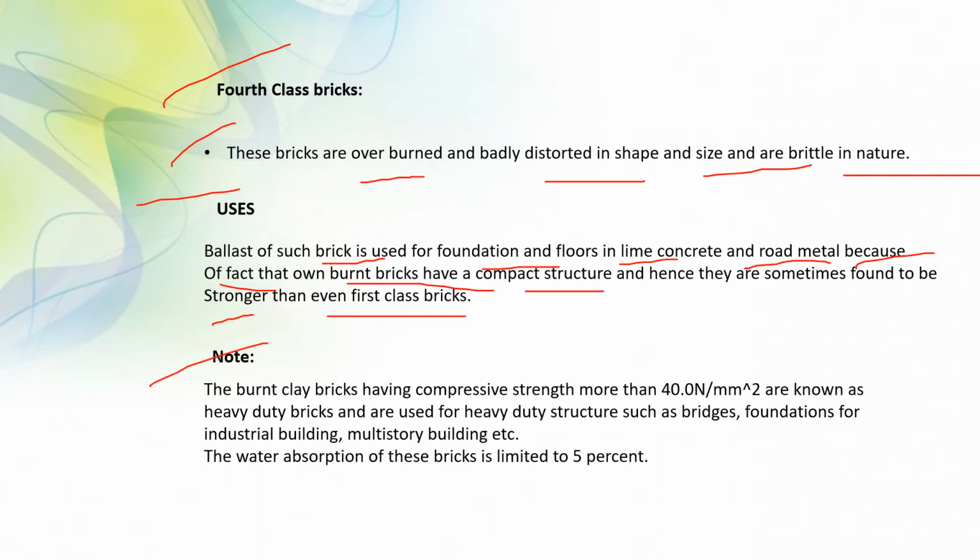There is some important note. Burnt clay bricks having compressive strength more than 40.0 Newton per millimeter square are known as heavy duty bricks and are used for heavy duty structures such as brick foundations for industrial buildings, multi-story buildings, etc. The water absorption of this brick is limited to 5%. So these are the four classes of brick I have discussed.